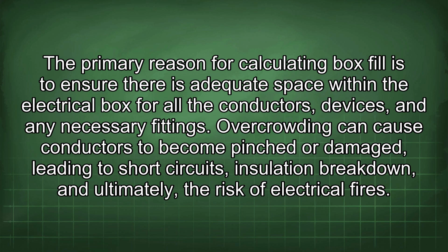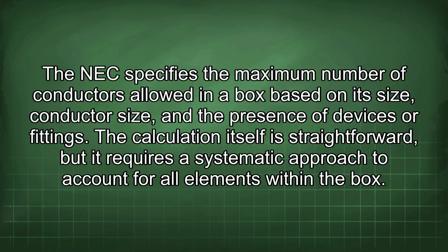The primary reason for calculating box fill is to ensure there is adequate space within the electrical box for all the conductors, devices, and any necessary fittings. Overcrowding can cause conductors to become pinched or damaged, leading to short circuits, insulation breakdown, and ultimately, the risk of electrical fires. The NEC specifies the maximum number of conductors allowed in a box based on its size, conductor size, and the presence of devices or fittings.